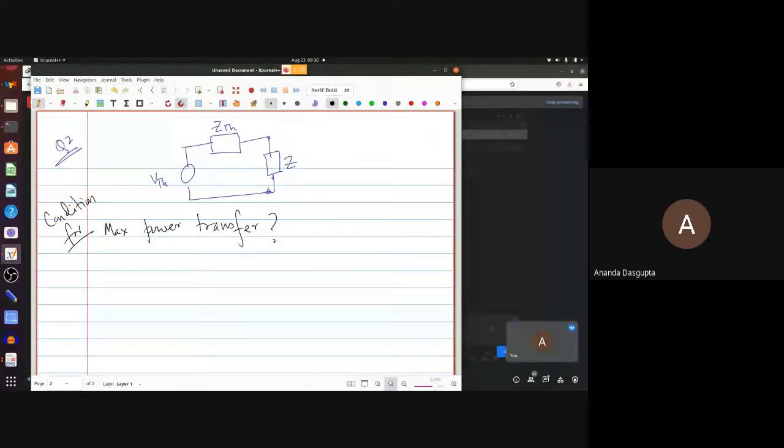Soham is saying load resistance equal to Z Thevenin. Is there a dissenting opinion? Sir, it should be the conjugate of Z Thevenin. Yeah, this actually is wrong. Of course, Z equal to Z Thevenin is a direct throwback to what you did in class 11, where maximum power transfer told you that R equal to RS, right? In fact, we made this problem earlier where we had pure resistances, and there we had said R equal to R Thevenin. But Z equal to Z Thevenin does not work, actually.